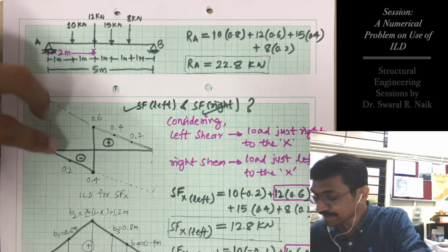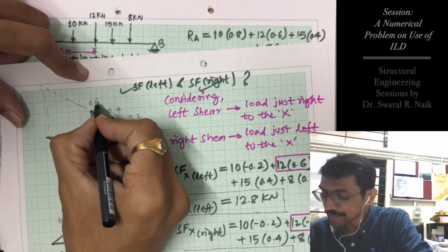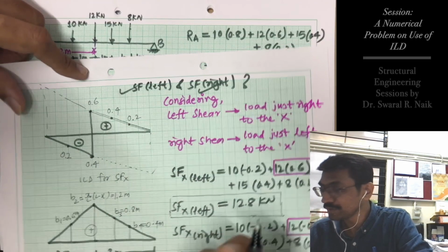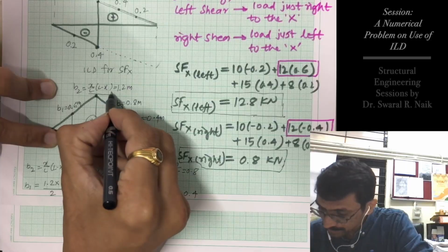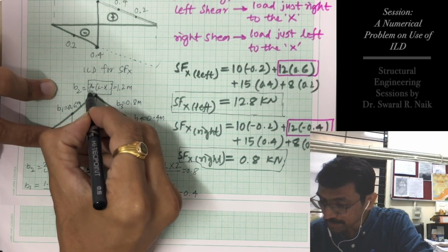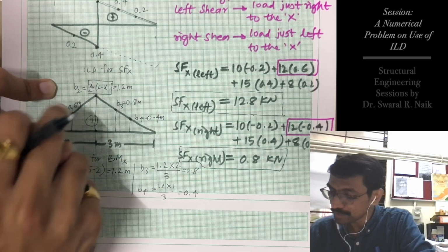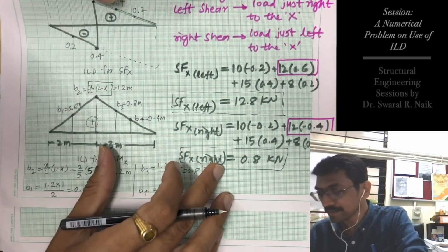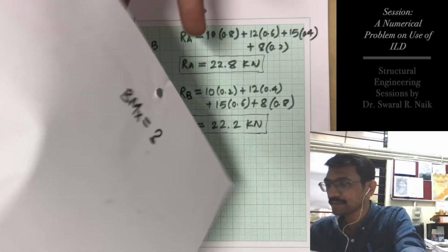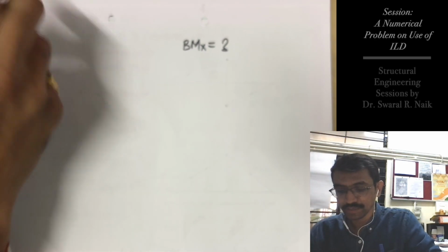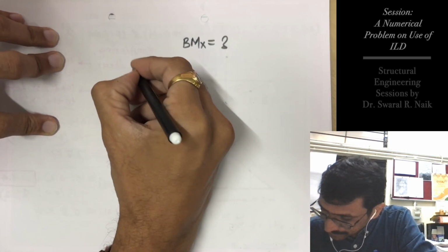Because you can see the equation x by L, x into L minus x. So there is no unit of distance. But here, you see this equation, x by L, meter by meter into meter. It means that this ordinate will have the unit meter. And when you multiply this ordinate with the loads, you will get kilonewton meter. Normal concepts of bending moment.